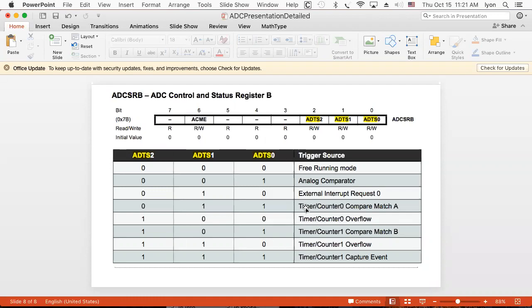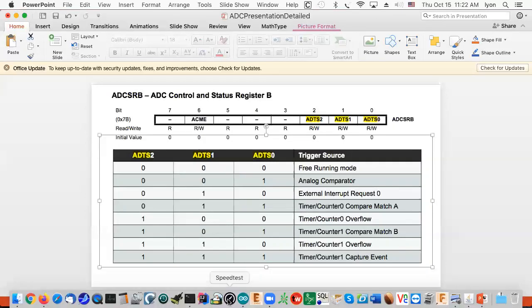And that works fine, because when the converter's done, we're going to go right in and start to take that data and output it to our DAC. So we're going to let it run as fast as it can. And if we change our prescaler in order to change the conversion speed, that's going to change the overall throughput of our system. And we've seen how that impacts the quality of the output that we get. It's a big deal. In fact, the way you hear it is a big deal, and also what it looks like is a big deal. So it's sort of an important quality control factor. And so that's my basic coverage of the code.